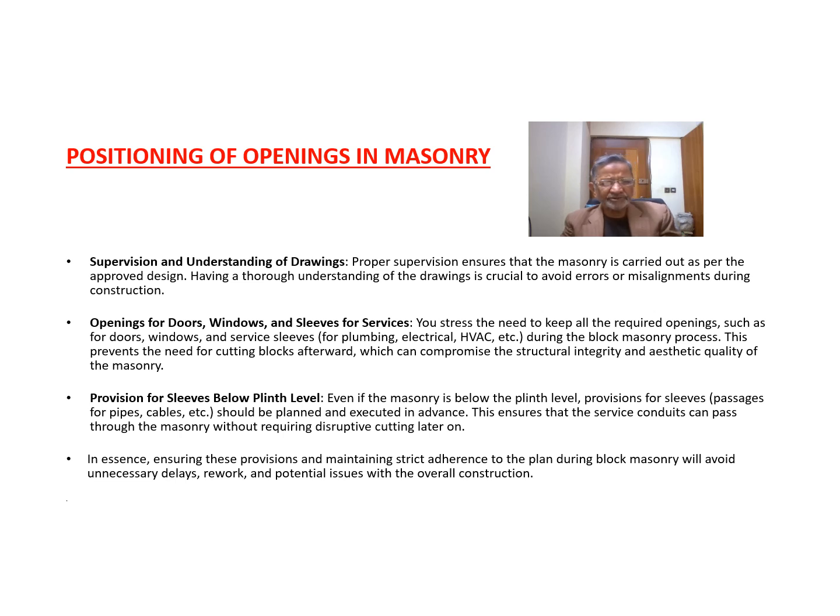A proper supervisor ensures the masonry is carried out as per the proper design. So the design should be thoroughly studied by the engineers. Openings for the doors and windows and the sleeves for the services: it is stressed that you keep all the records of required openings such as doors and windows and sleeves for the plumbing, electrical, HVAC, etc. in block masonry, so that there should not be any cutting in future.